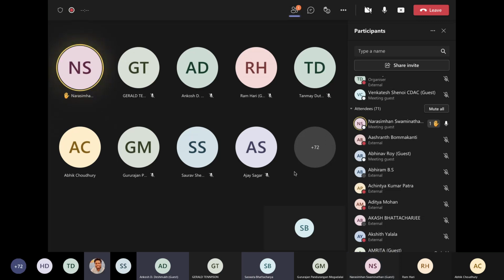Misfit effect comes because of the phases, right? But I am not talking about the misfit strain effect. Other than that, this is like a solid solution effect, right? That is already included in the omega. Yeah, so that can be included again as a superposition principle, where you write down the solution thermodynamics without that term, and then you put in misfit. That's what we exactly did. And then you create a superposed functional which will have all the stress effects. Exactly. So does that mean that most of the times you see phase diagrams at constant stress, and you can modify the phase diagram as a function.